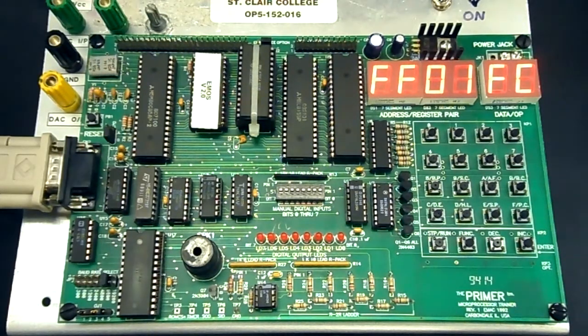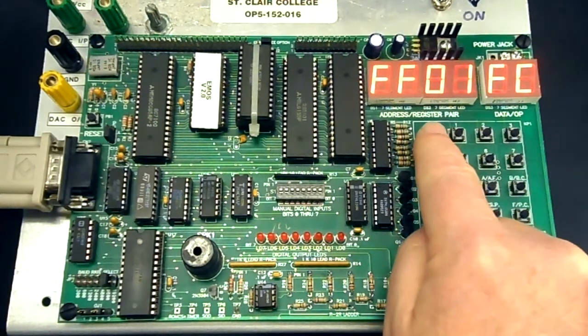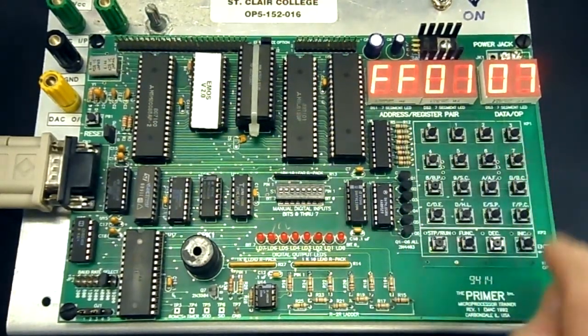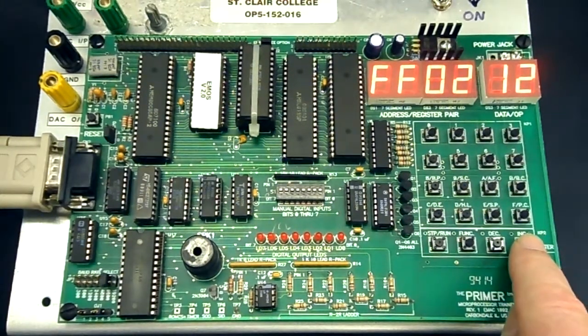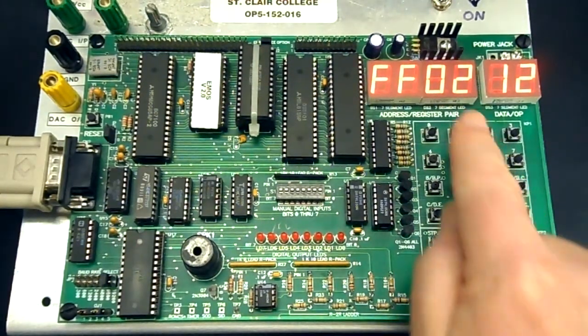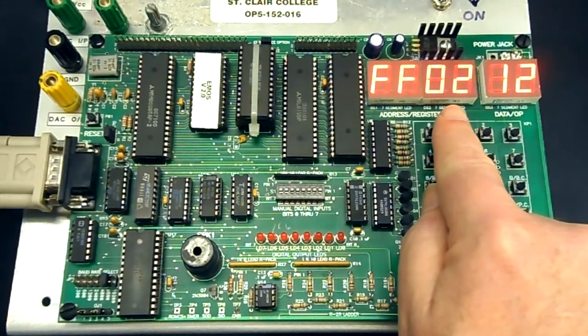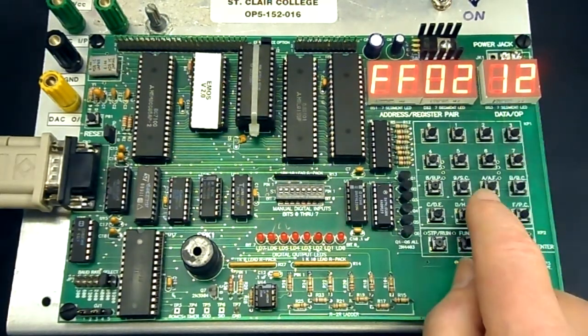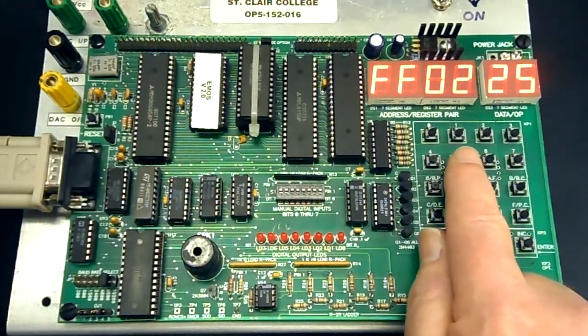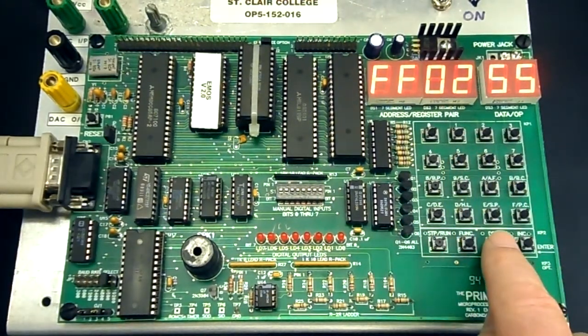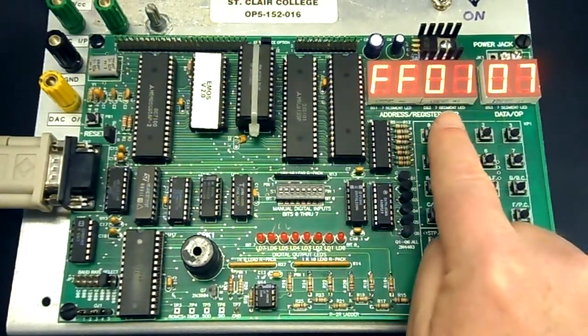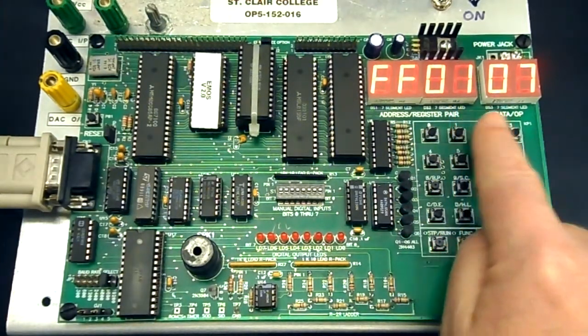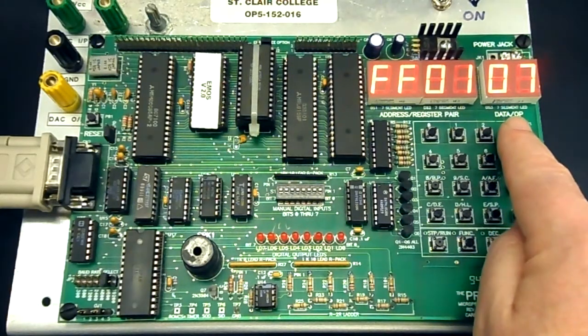Okay. It now says to type the numbers 0 and 7 and press Enter. So 0, 7, and then Enter. Okay, so the program counter has been incremented to FF02, and we're now seeing what's in memory location FF02. Now they want us to press 5, 5, and press the Decrement key. So now we're back to FF01 and we have the new data that we typed in, 07.